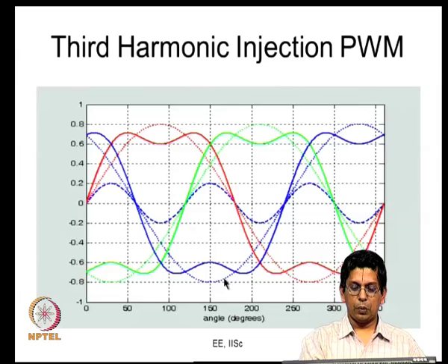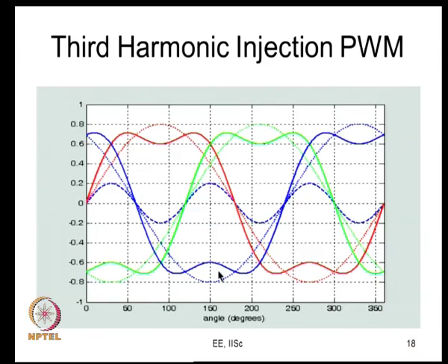Alright. So, now you go PWM method by PWM method. I said that this procedure is common for anything, so it is not just sine triangle PWM. What I have done is, on this modulating signal, I have added a common mode signal for all the 3 phase modulating signals. So, your R phase signal looks like this. The common mode signal is a third harmonic signal, which is why I call this third harmonic injection PWM. We have seen this before. Now, what should I do? I must calculate the duty ratio based on that. What happens in the duty ratio?